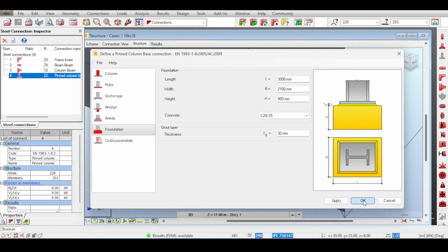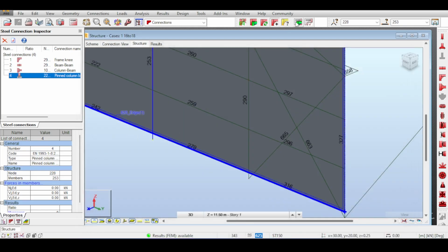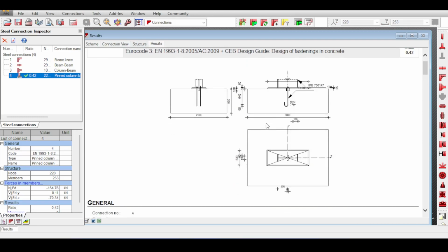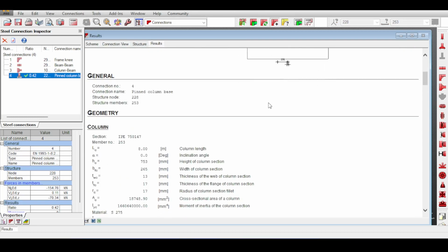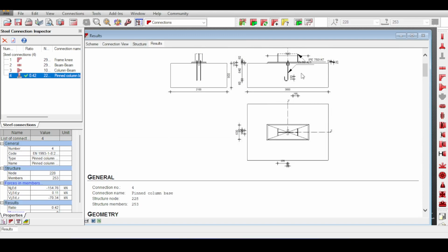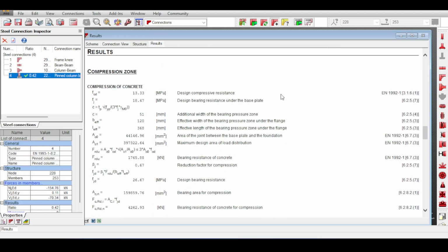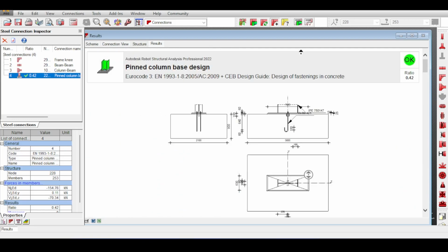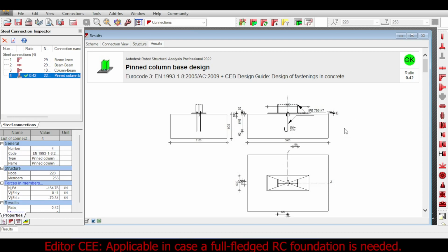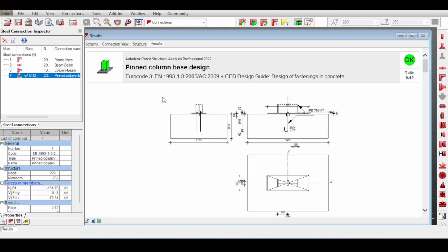If you click on OK or apply and calculate, then you can get the design of the foundation with its anchorage. Here, there are no details as for the concrete foundation used here. There are absolutely no details. Okay? There are no details because the idea here is to design the connection to the foundation, not the foundation itself. So after you finish the connection to the foundation, you can use the dimensions of the foundations to go back, and this becomes a back and forth issue.